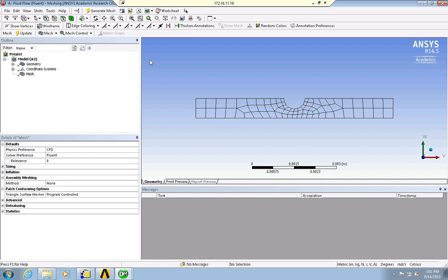The problem with the mesh is that you are only going to record velocities and pressures at center points of each element. And that's problematic here because essentially you're only going to have two pressures and velocities at the inlet. And we know that you would expect a parabolic velocity profile, but if you only have 2 points, you're not going to see that. So the mesh needs to be finer.